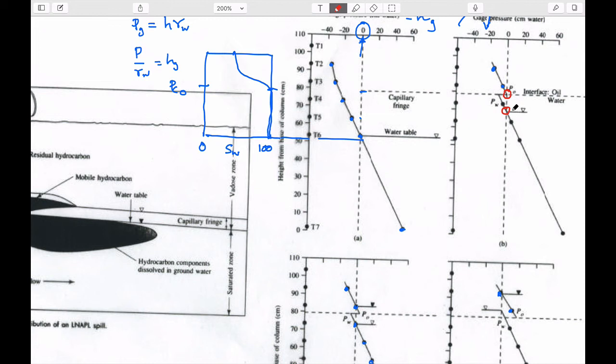And so since by definition the water table is where the pressure is 0, there are two tables, water tables. You can decide whether they're water or not. But this one here is definitely water. But what it's doing is that the oil that's coming down on here, gasoline above here, and water below, is compressing this capillary fringe and giving you an oil table and a water table. So this is the interface between a partially saturated zone and oil, and then a tension saturated zone of oil above it. And here this is the capillary fringe which is being compressed.